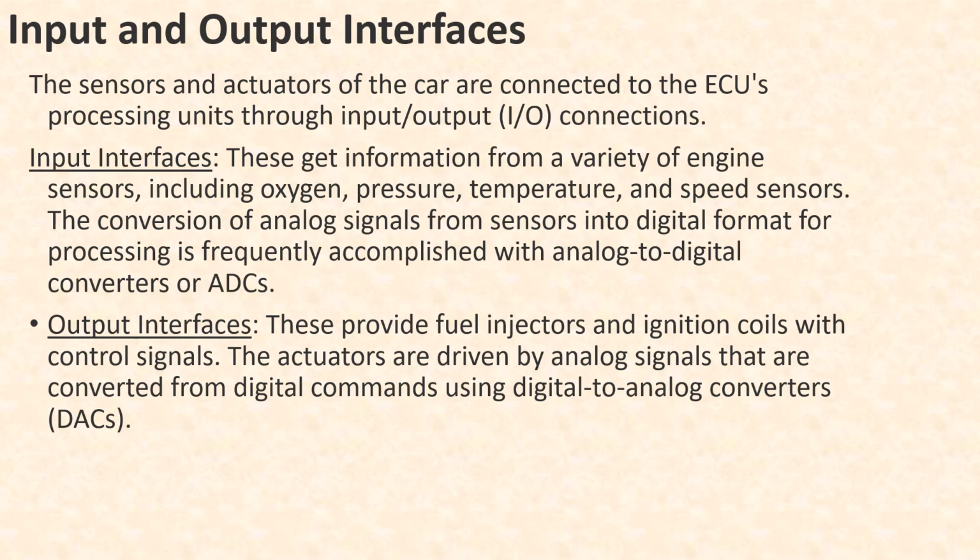All right, now the output interfaces. These provide the fuel injectors and ignition coils with control signals, and these actuators are driven by analog signals that are converted from digital commands using digital to analog converters. Now let me point out that there is a separate session which I have prepared for actuators, but that particular session is strictly for ADAS actuators.